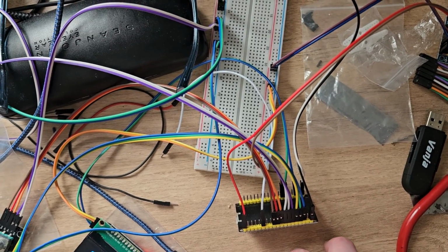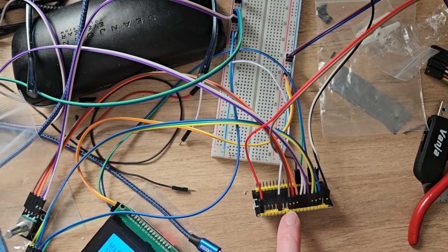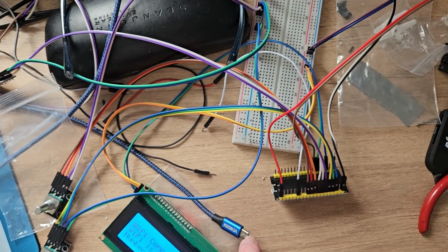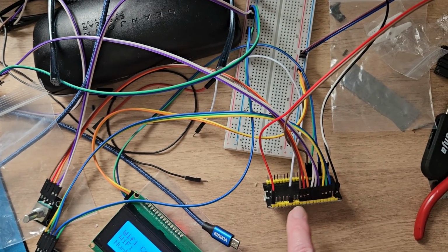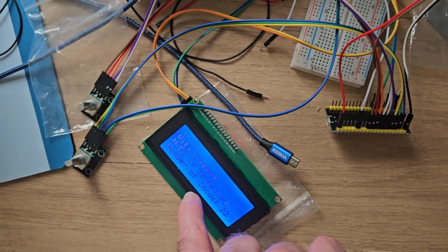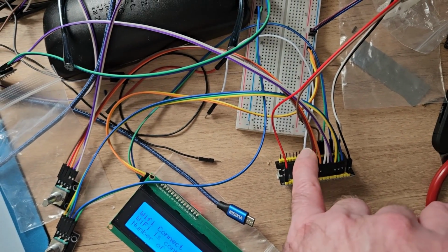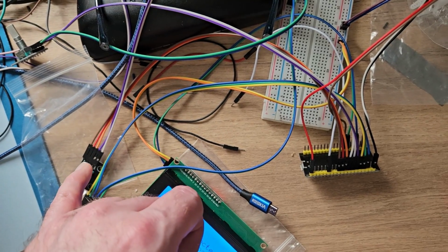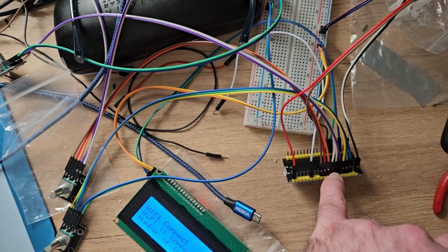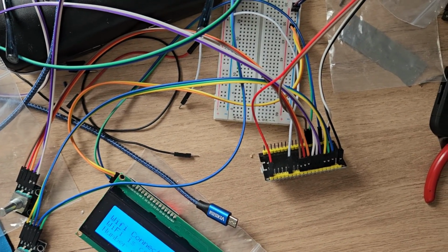I'm a bit of a beginner with electronics, really, but what I realised was that the ESP will take a 5 volt supply as its power. So that's pretty much what it was taking from the USB. So you just replace the USB with a 5 volt supply, and the screen wants a 5 volt supply as well. And then the ESP has a 3.3 volt out, which is what goes to all of the knobs, so that they can supply 3.3 volts on the input pins, because that's the maximum that the ESP can comfortably take on an input pin.